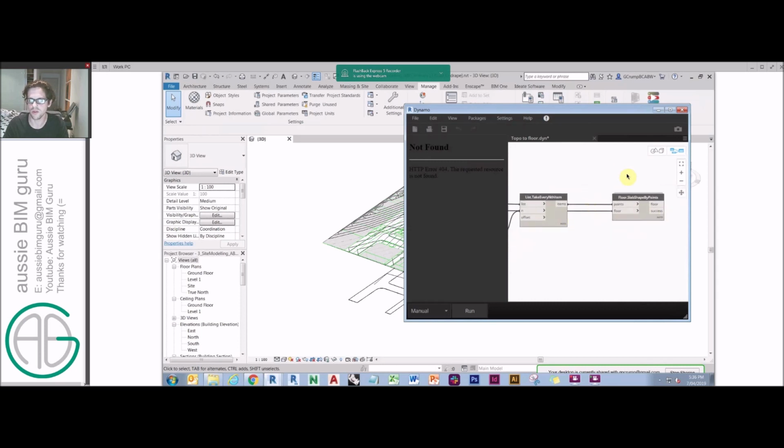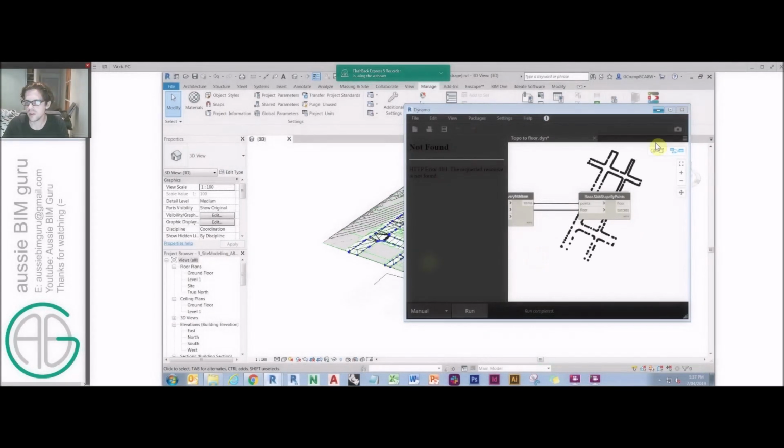In this case, we want to use all points. And I'm just using a node here, Floor Slab Shaped by Points, which I believe is from the Clockwork package, but there's a lot of packages that have this node as well. If I run this, which will typically take about a minute, maybe a bit less in most cases, it will...